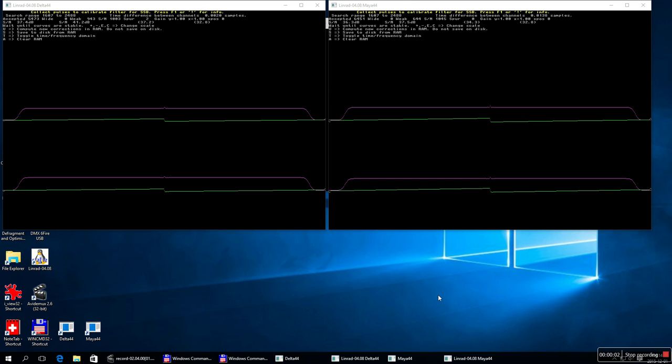I have started the calibration once more, and you can see the amplitude, the magenta, is very flat because the system is already calibrated. So now I am trying to make an improved calibration. And you can see the time shift between the channels, 0.002 or 0.01 in the two sound cards.